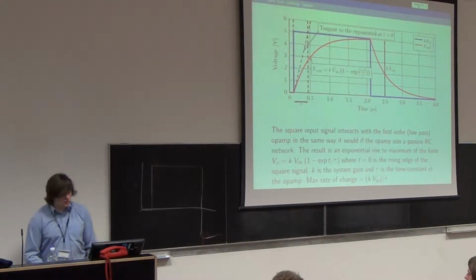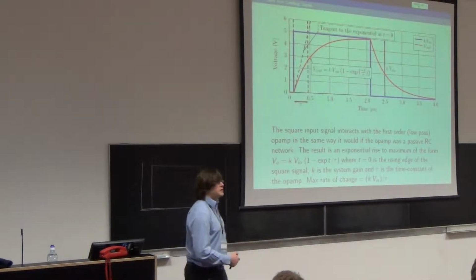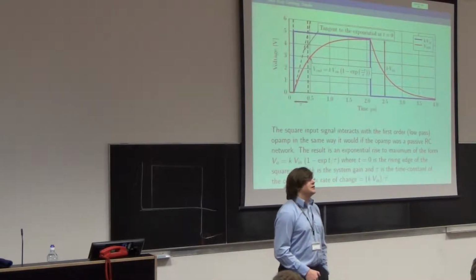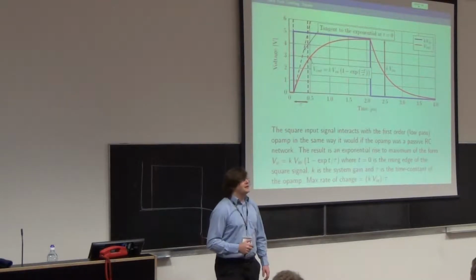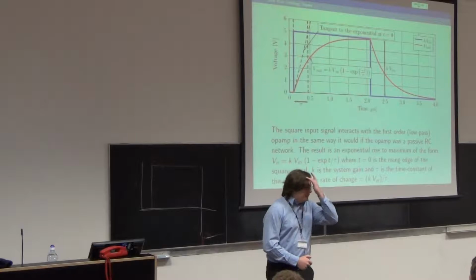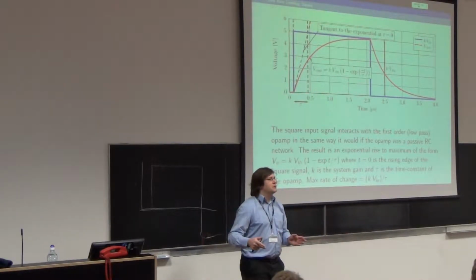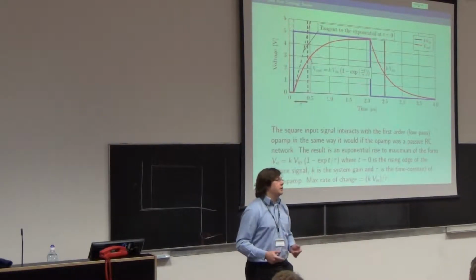It is essentially a first order system. If you're wondering how I made such a lovely graph, I got an RC network, put it through Spice and plotted it. Because if you do it with an op-amp in Spice, it doesn't look like it should in the textbook because the op-amp's a bit too clever and it knows what you're up to. Well, it doesn't know. The op-amp that you look at in Spice is not necessarily made up of 3 first order circuits all bolted together. You can make an op-amp like that and it works alright.